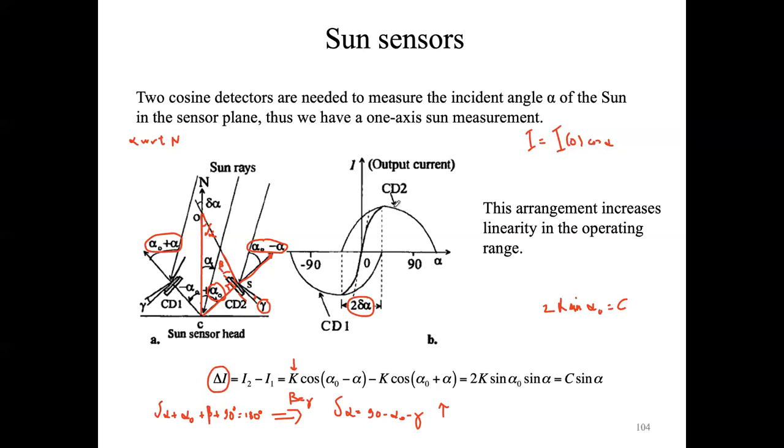And that's true, because if you do, for example, this one minus this one, you get an ambiguity in the signal of the sun sensor. Since this one is 0 for this angle, it gives you this value. At angles larger than delta alpha on this side, since you have to do this signal minus this signal, these two amplitudes are equal, so you are not able to disentangle the effects outside these two delta alpha.